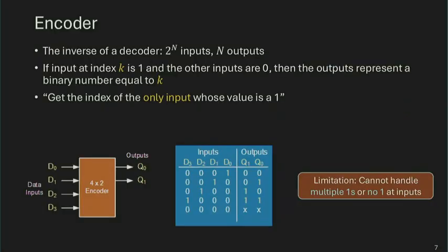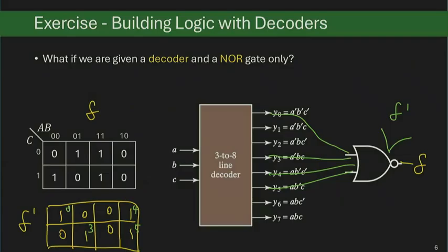Similar to what we did with that singular max term from yesterday's example. Or the other way to think about it is that there's an equivalent where you can think of this NOR gate as an AND gate with inverted inputs. So every minterm becomes a max term. You're essentially collecting the indices of the max terms to construct the function.